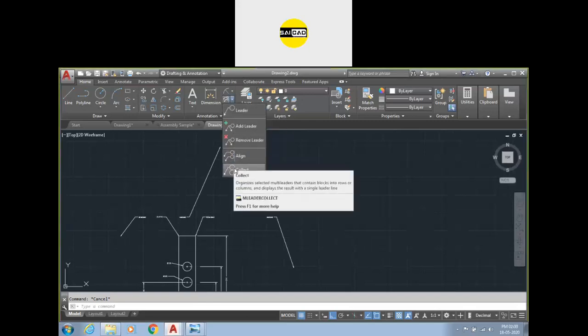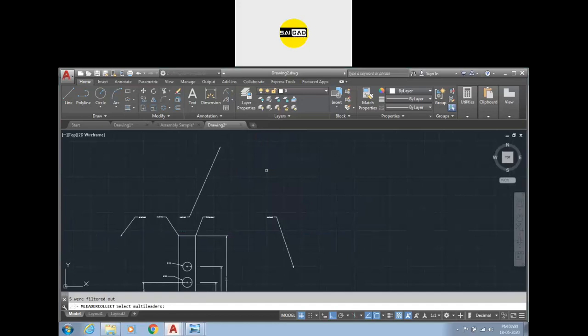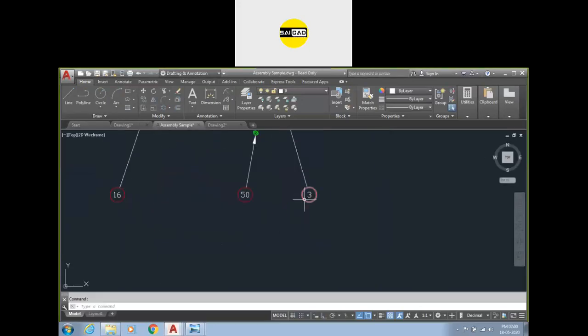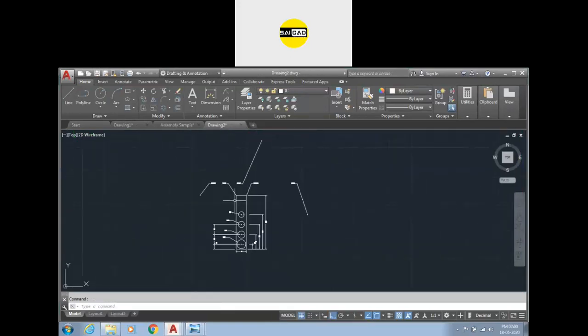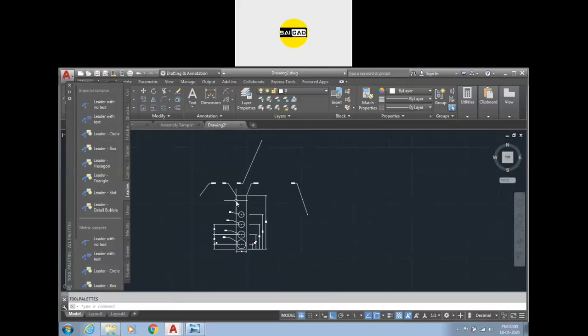So the last option is collect. It is not used in this type of leader. You will not be able to select it from here. For this command, you have to specify some other type of leader. Now, if I show you, there are some leaders with a circular shape. You can see with a circular shape, how can we add that type of leader? To use that type of leader, we have to go to the library. For that, press tool palette, TP shortcut and enter.